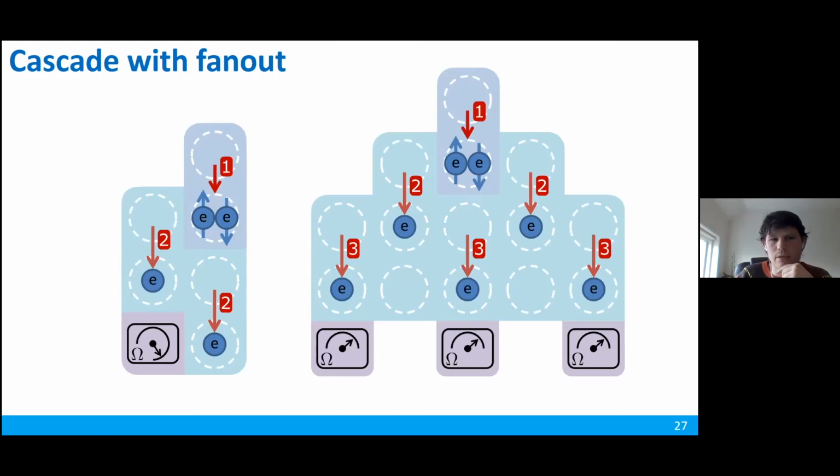And in this case, they could occur at the same charge sensor. So for this charge sensor, there's now an even stronger change in its environment. So the signal would be even stronger. Or alternatively, perhaps one could fan out these different cascade paths further and then use multiple charge sensors, which each have a charge change in its environment, and by that achieve a higher readout signal.